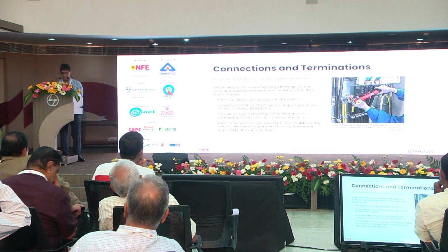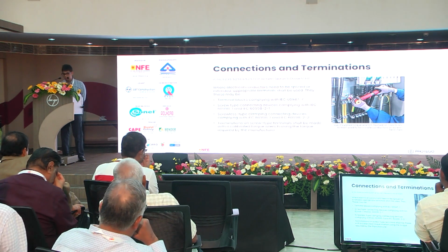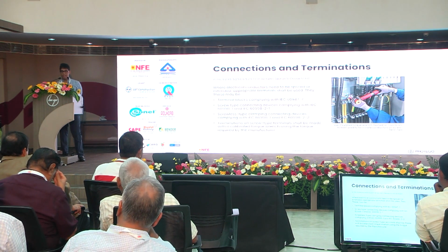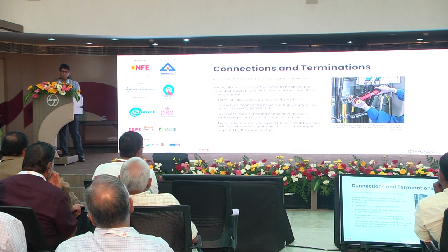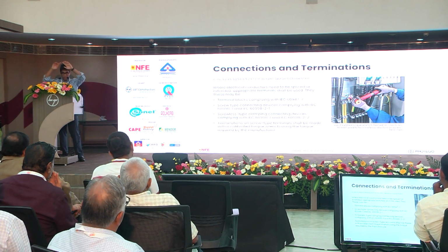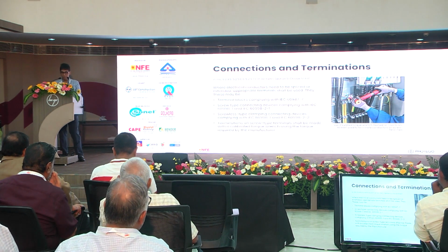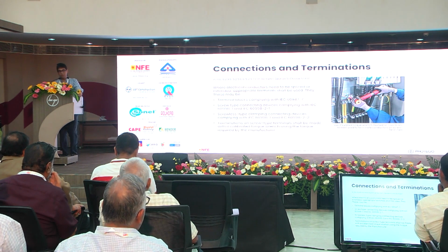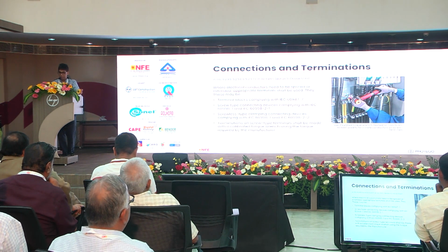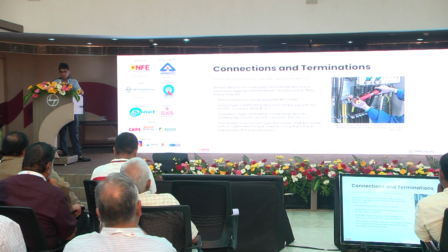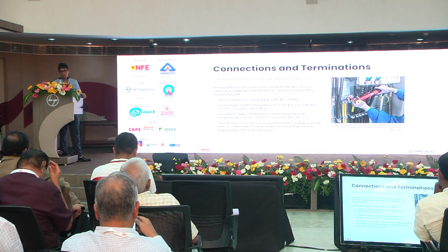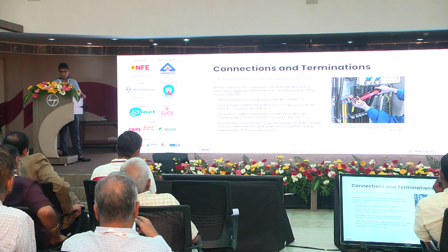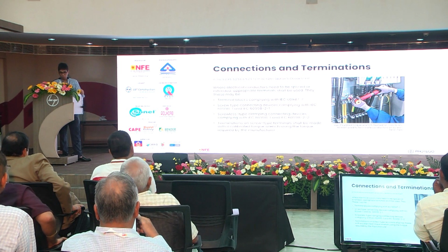See, when connections are made, appropriate terminals need to be used, and these need to conform with their product standards. Like I said, to meet the performance requirements of 732 and NEC, you need to use products that conform to certain other product standards, so you can meet the overall product standard of performance. If you're using a terminal block, it has to comply with the requirements of 60947-7. Screw terminals like the ones we saw earlier need to comply with 60998-1 and 60998-2-1. 60998 is for connecting assemblies, 2-1 is for screws.